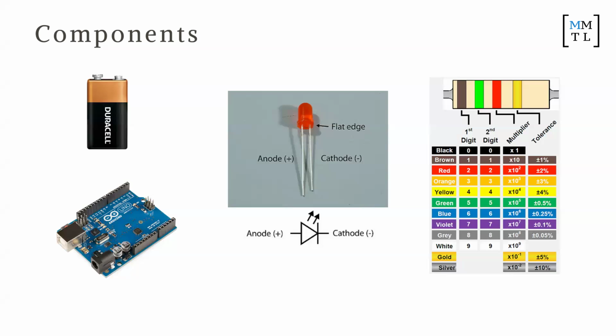Now, how LEDs work is that there is a polarity. I've been caught out before in one of my past projects where I screwed up the polarity of a different component, so you have to make sure that you get your polarity right. This here is considered the anode or the positive terminal. This is the negative terminal, so you can see by the length there. There's also another mark there, which is that the flat edge is on the cathode side.